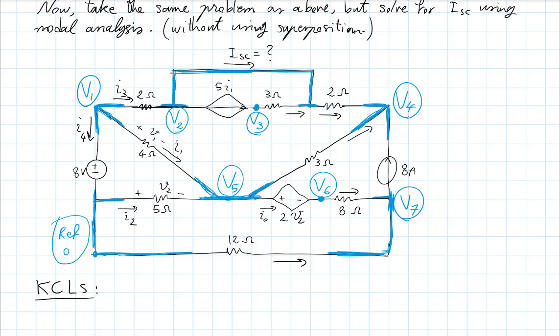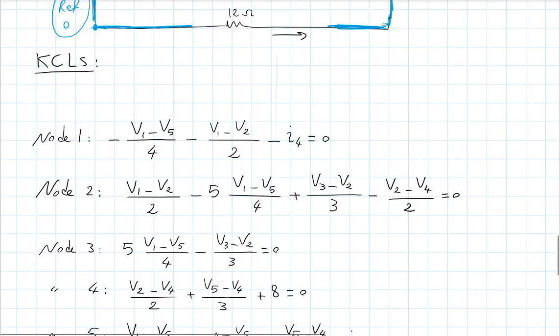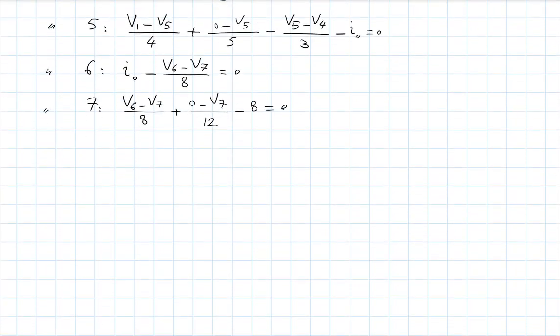First of all, those are the pieces of information that come from the voltage sources. They introduce this new unknown for me, but they also do their share of providing information. So if you look at the 8-volt source between those two nodes, the reference and V1, what does that mean? If you want, this was the equivalent of KVL, that the voltage of the element is just the difference of the node voltages on the two sides. So 8 volts is the difference between V1 and 0. So that's another piece of information that we already have. So additional pieces of information.